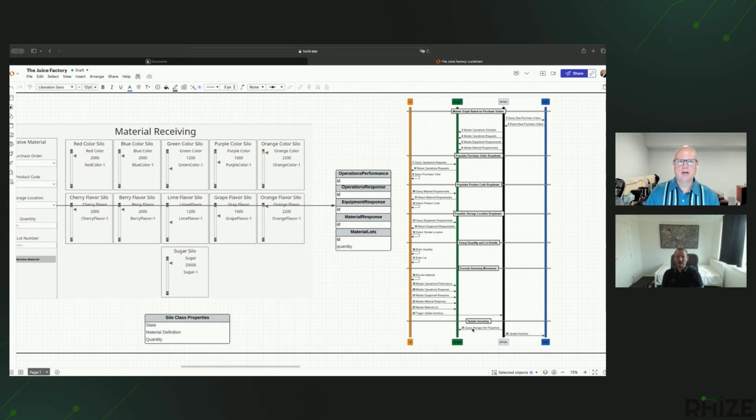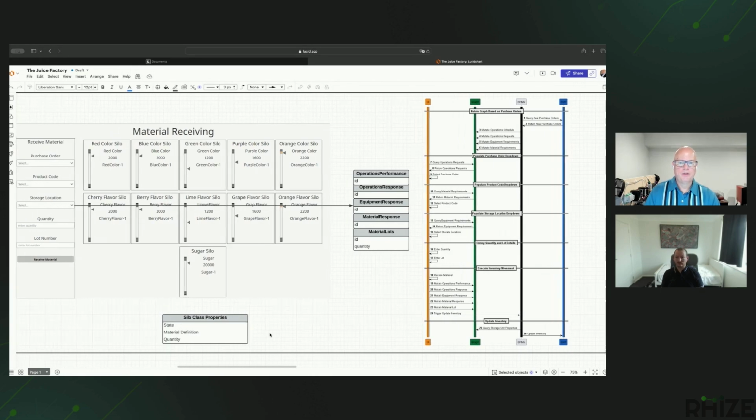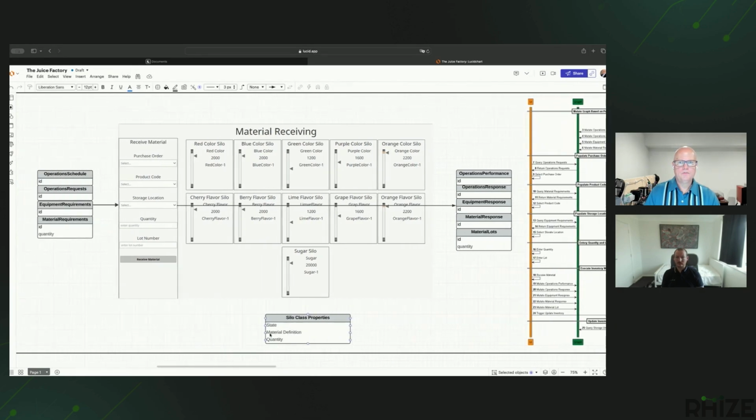But there's generally mechanisms for how we account for that. We say there was 500, the level says that there's 450. We'll have different ways, because you might have a weigh scale and a level gauge, and they may use one as what we talk about as custody transfer. One's going to be the source of truth for that particular event, but that would all be accounted in here.